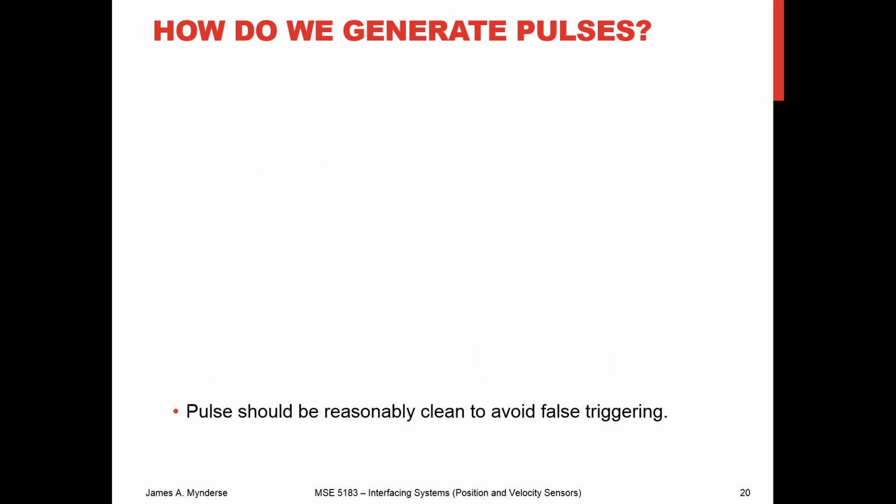I mentioned mechanical switches just because that's the first thing that I think of as being sort of intuitive. But what other types of switches might you see? Well, you might see magnetic, which we were looking at with Hall effect sensors, and when we looked at Hall effect sensors, we mentioned that we could have a toothed gear or something going around that the Hall effect sensor is going to periodically see one of those teeth and register it as a pulse.